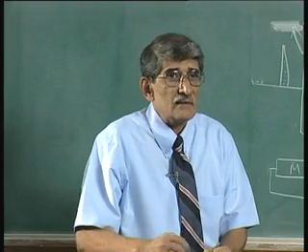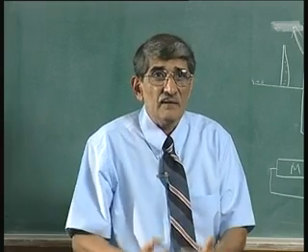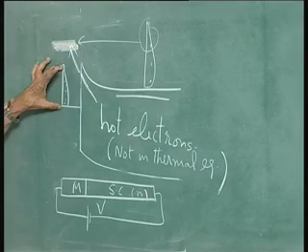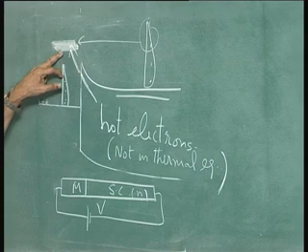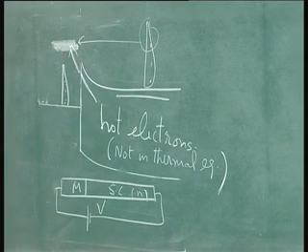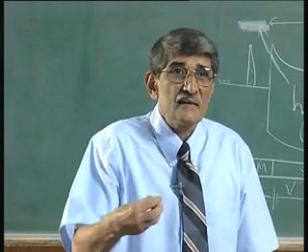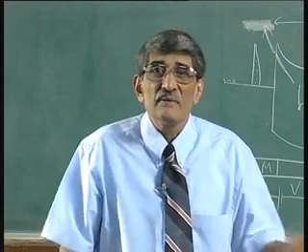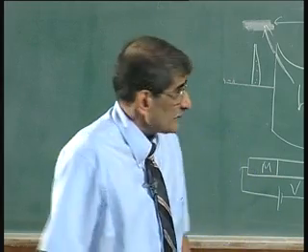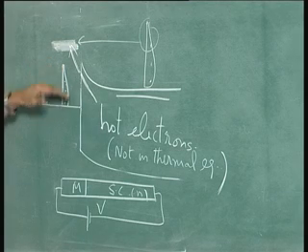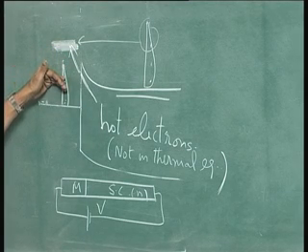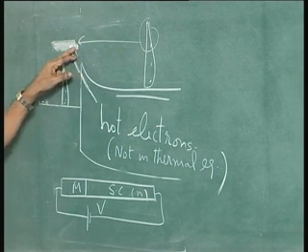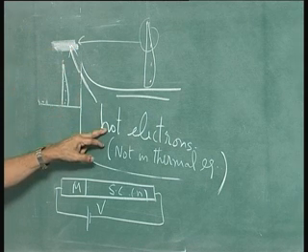That means their energies are more than those of electrons which belong to the metal. Usually, the electron exchanges energy with the lattice, and it is in equilibrium with the energy of the lattice, that is, the room temperature or whatever is the temperature of the metal, whereas this is higher than that. It looks as if the temperature of those electrons is more than the room temperature. That is why it is called a hot electron. It is hot compared to the electrons which are in thermal equilibrium with the metal. The same electrons here can occupy higher energy levels if you heat up the metal. Here, without heating, they are at higher energy, because they belong to this metal and cross the barrier. That is why these electrons are called hot electrons.